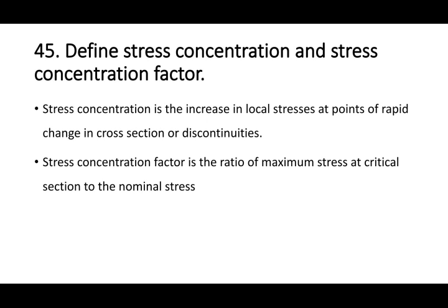Next question, define stress concentration and stress concentration factor. Stress concentration is the increase in local stresses at the point of rapid change in cross-section or discontinuities. Due to change in cross-section, the stresses will increase rapidly. That is known as stress concentration. Stress concentration factor is the ratio of maximum stress at the critical section to the nominal stress.